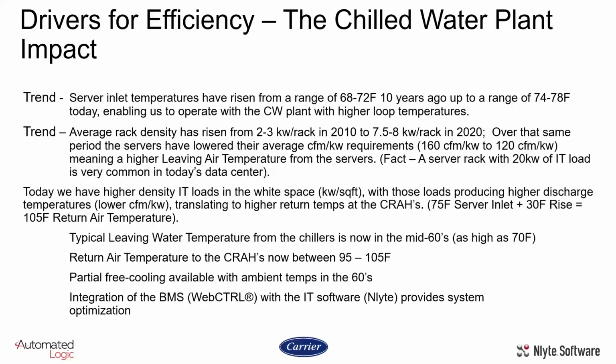So now we have higher density IT loads, meaning more kilowatts per square foot on the white space floor, with those IT loads producing higher discharge temperatures. This all translates into higher return air temperatures at the computer room air handlers. For instance, if we start with a 75 degree Fahrenheit inlet temperature at the server and have a 30 degree Fahrenheit rise, we end up with a 105-degree Fahrenheit return air temperature to the computer room air handler.